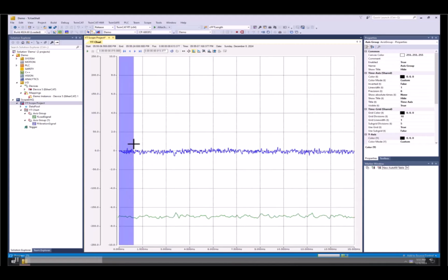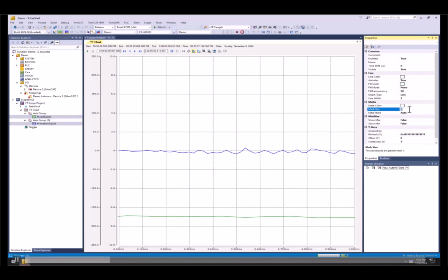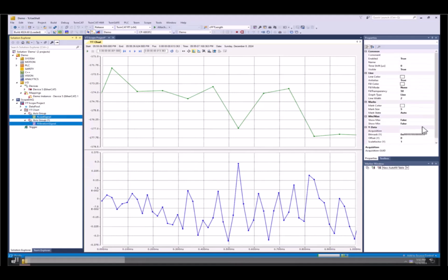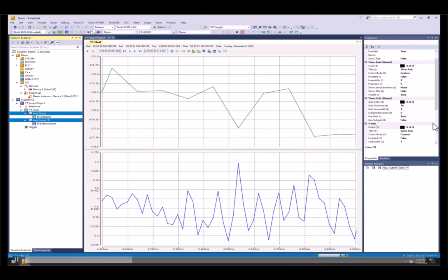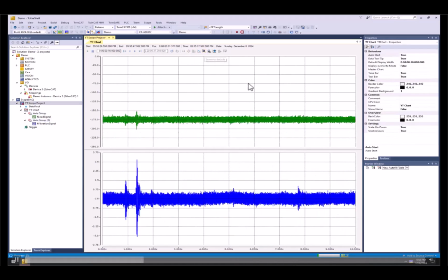I can also zoom all the way into the time scale for our PLC cycle or driving cycle time. And we can actually validate that we are getting the appropriate amount of data points for each of the signal interfaces as we could count it out. So it'd be 10 on the top for the load cell in green and 50 on the bottom for the vibration signal.